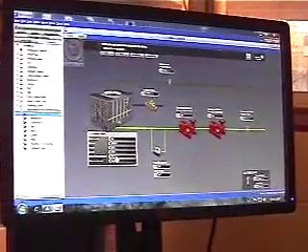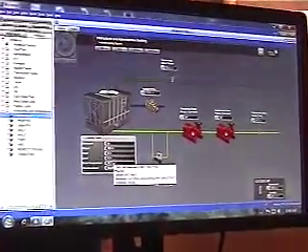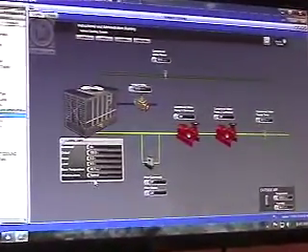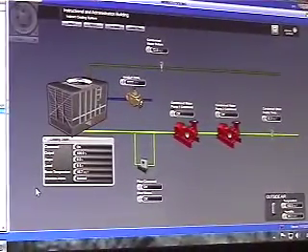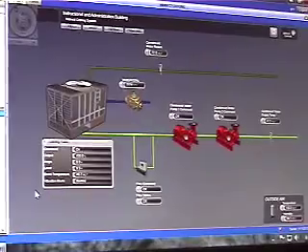That's all done through the float inside the base of the tower. We have a basin temperature right here. That's just the temperature inside the basin, as well as a vibration alarm. The way the basin temperature works is that whenever there's water in the tower, and if your basin temperature gets below, I believe it's 35 degrees, for more than about 5 hours, it'll set off an alarm letting you know. If there's no water in the tower, it's not going to give you an alarm. So it's just an indication that, uh-oh, we forgot to drain the tower or whatnot.